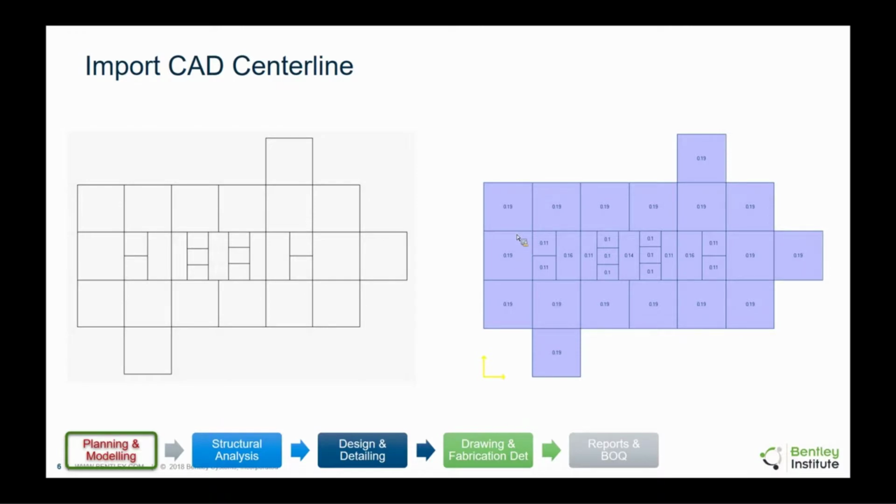So let's say we suggested some thicknesses here, and the engineer wants to change it. Let's say there are some slabs which are 110 mm thick or 160 mm thick and so on. You want to change that to the same thickness, or increase it, or a lesser thickness. Once you do that, the consequences of that are taken care of by the software. So you take the engineering decision to alter the size of the member. Everything else, which involves impact on the self-weight, so automatic calculation of self-weight, impact on computation of lateral loads and so on, is automatically accounted for by the software.